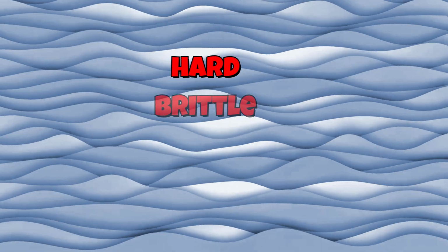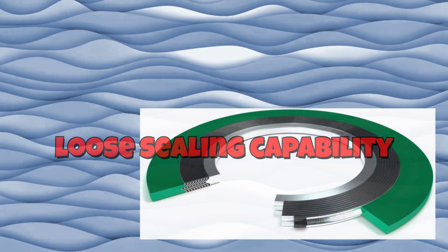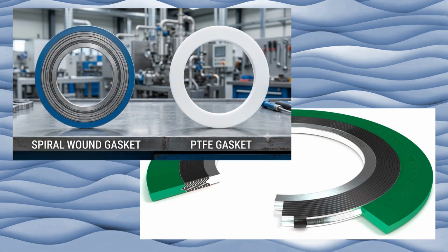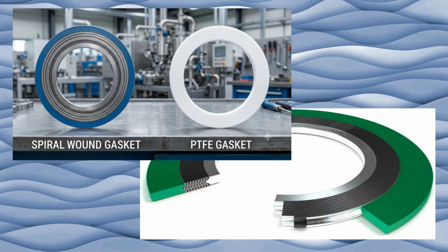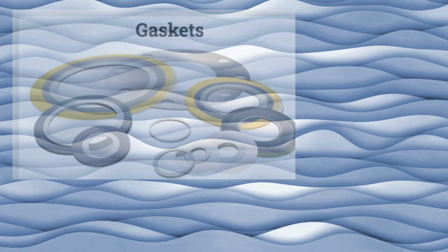Standard rubber seals don't survive cryogenic service. They become hard, brittle, and lose their sealing capability. Cryogenic systems therefore use specialized sealing materials such as Teflon, and spiral wound metallic gaskets with graphite or PTFE filler. Choosing the right gasket is just as important as choosing the right pipe material.